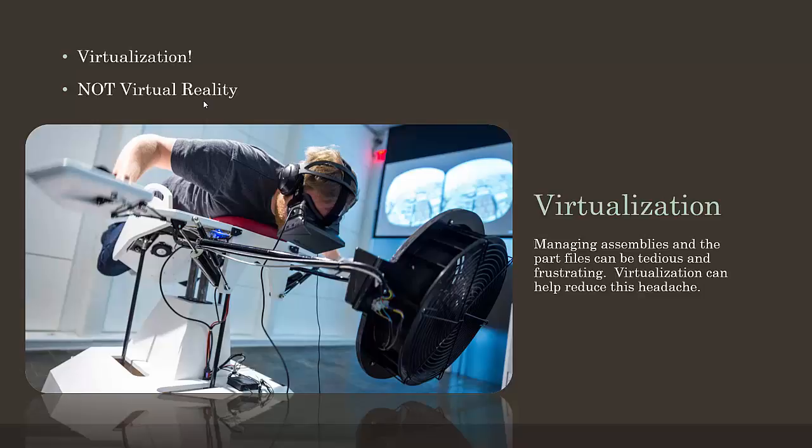You are looking at the preview data that is stored. In fact, that is the biggest part of an assembly file, this 3D preview that you see. It's the same reason that you have a part that's updated. So when you open up the assembly, you zoom into the part, it's not right. And then all of a sudden it goes click, and then it turns into the right part. You're looking at the saved virtual 3D data that's in there.